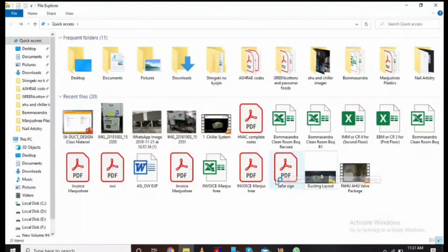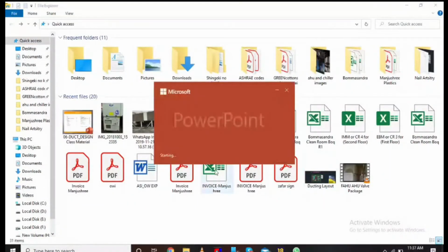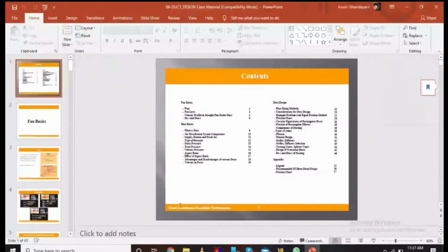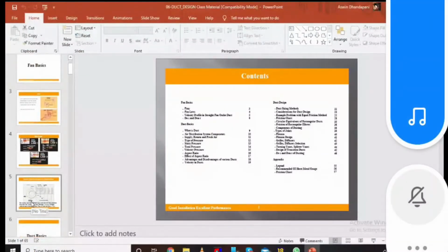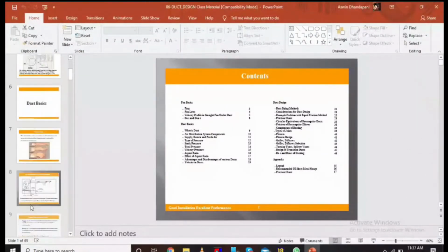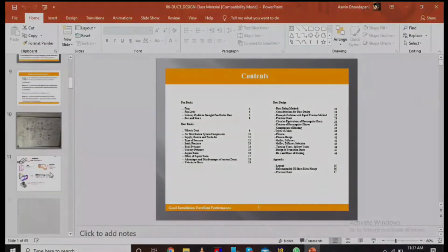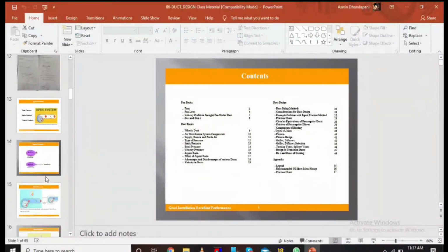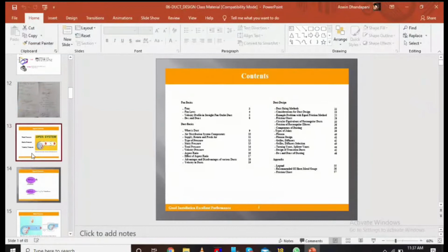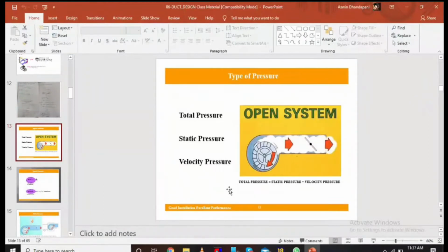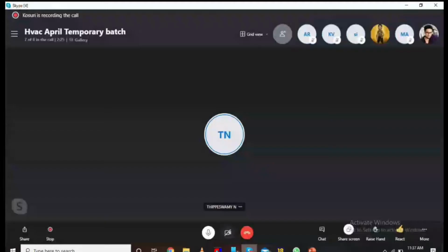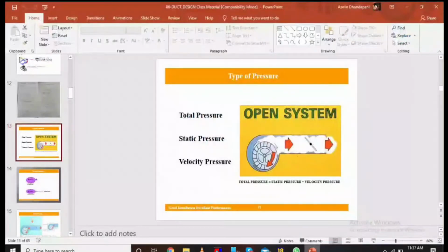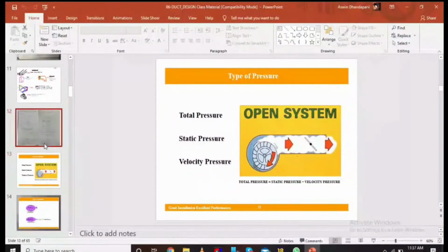and other things I told you, right? Yes, sir. Duct sizing, Q equal to A into V. Then again your reducer, W1, W2, H1, H2 into length, all your duct fitting pieces, then your shoe neck, elbows. I think I have to start from pressures, guys. Okay, different types of pressures. Air distributing system components.